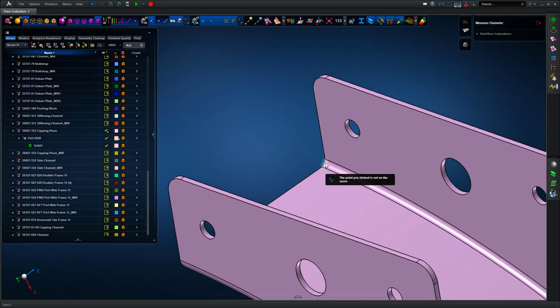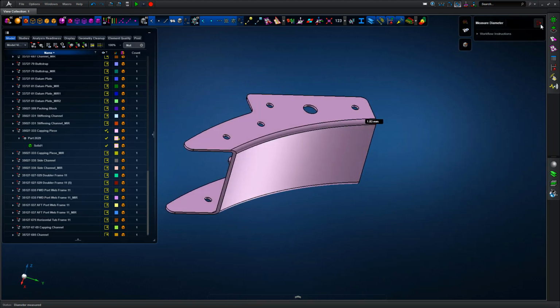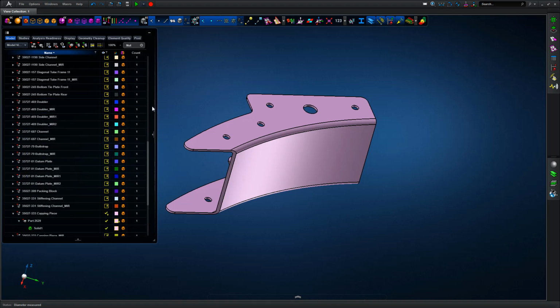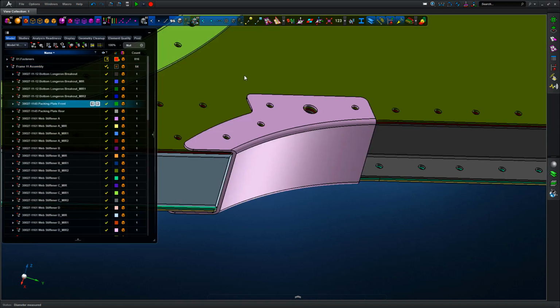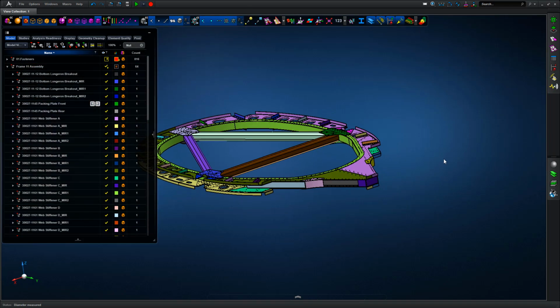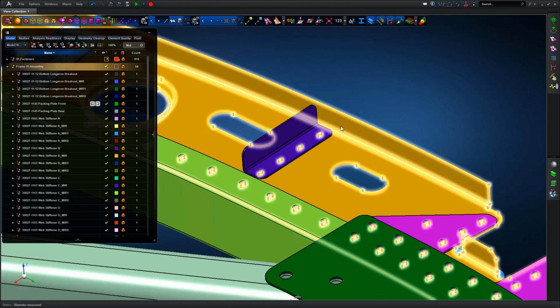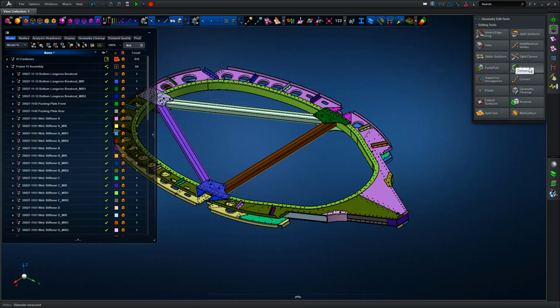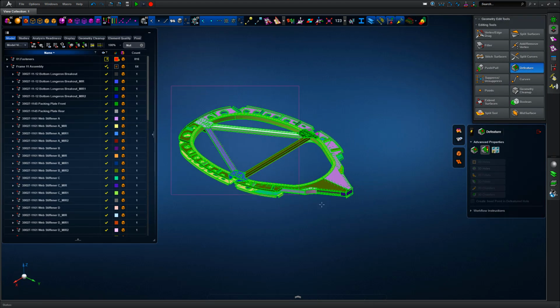So in this case we're going to use some of the measurement tools to measure a fillet, and we're going to use that dimension for a subsequent defeaturing operation, which we'll be performing on the full assembly. Remember, we've taken out all the fasteners, so we're effectively reducing the complexity of the model, or simplifying the model, and we can see how some of those fillets are controlled in the specific areas of each model.